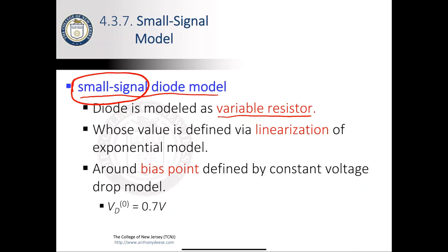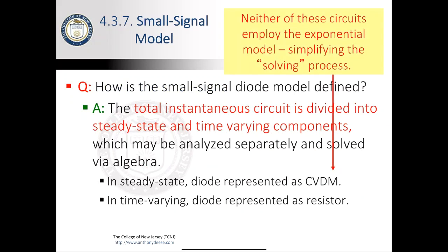One good example is the one that we worked through, which was a voltage regulator. That's a case where we are looking at the effect of small changes in the voltage across the diodes. Now, it's not so good for examining applications such as a rectifier, right? Because for a rectifier, we would have the voltage most probably varying over a wide range, 5, 10, 15, 20, hundreds of volts. And that's pretty obviously outside of the expected use for this model.